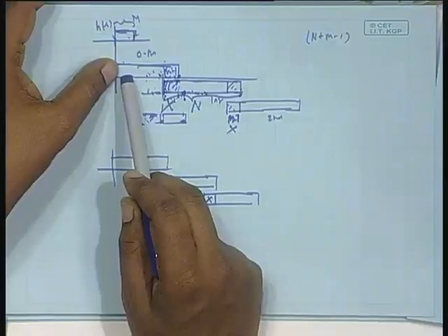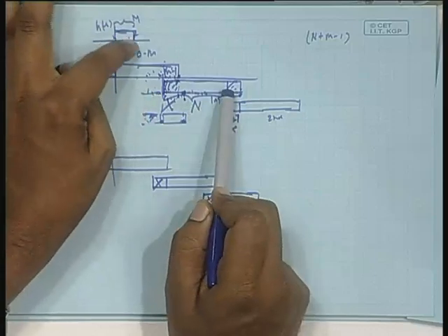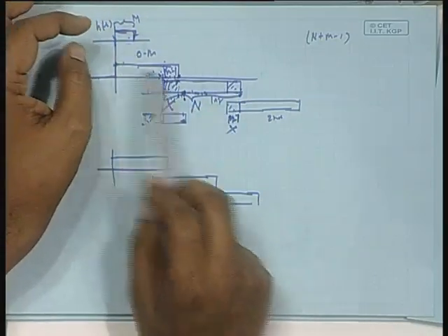Okay, this is overlap and save. So, you understand how it will be used in the adaptive filter case, not weight updating I am talking of now, I am only talking about the filtering part. For this block, one set of filter weights, for this block another set of filter weights, but for this block, say this is the filter weight. I have to convolve between this and this block.